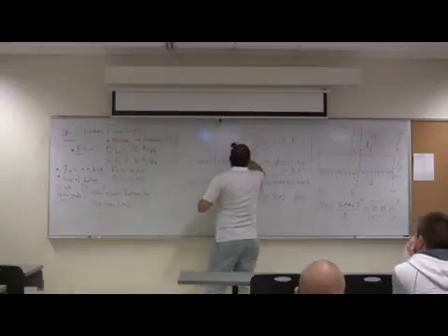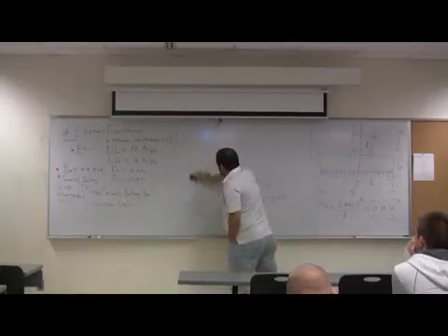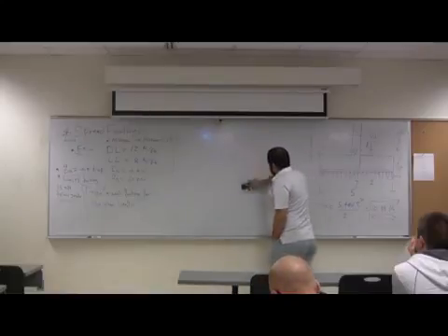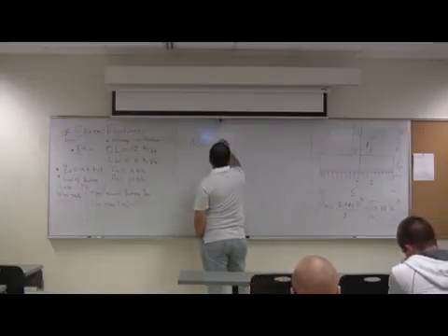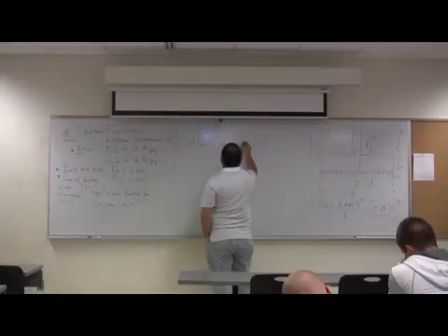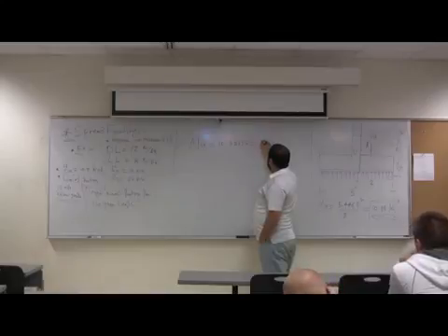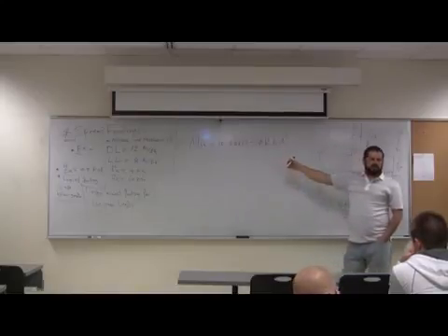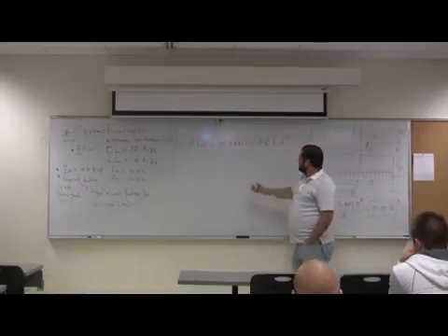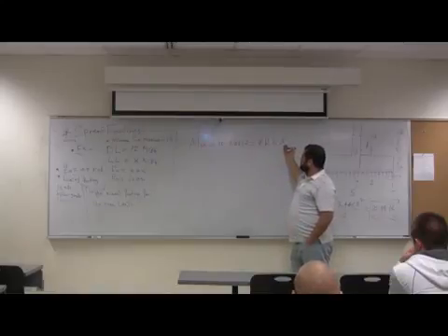So shear is checked. When I tell you check shear, that's how you check the shear. Now, Mu equal what? 10.88 kip-foot, right? Times 12 equal phi R b d squared. Have you seen something like that? Mu equal phi R b d squared. So this is in kip-inch now. Those will be in inch.